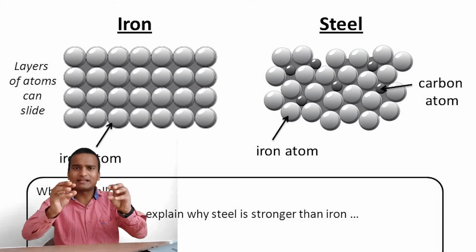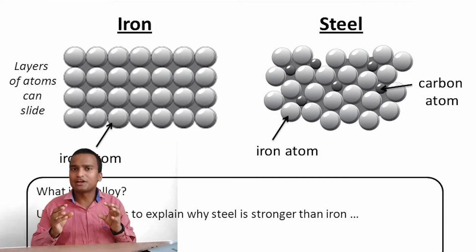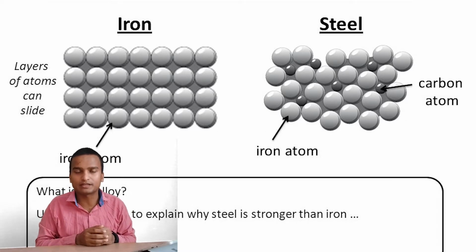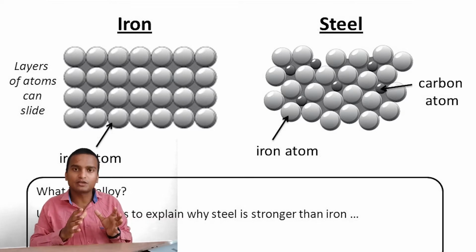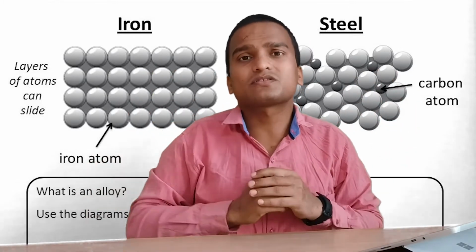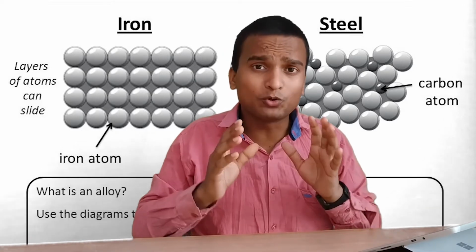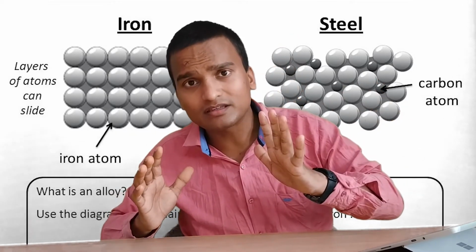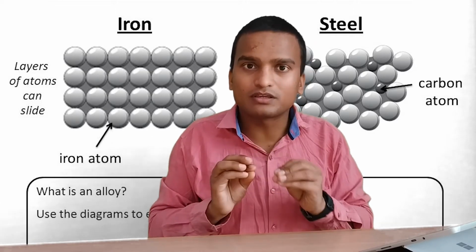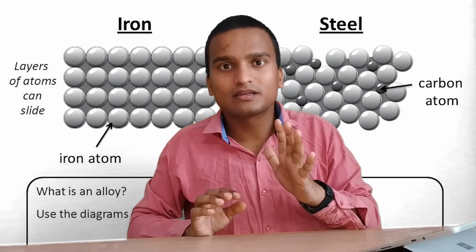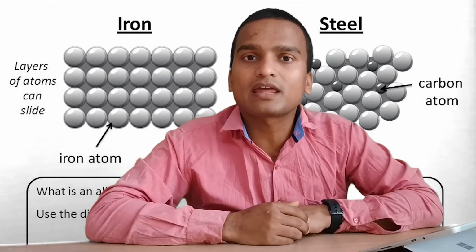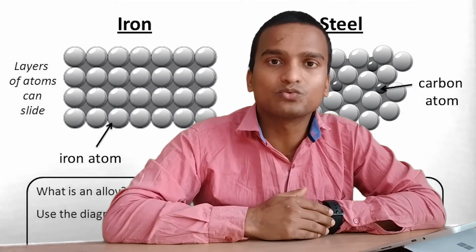Now look, there is an iron lattice which has 8 or 10 or 12 iron atoms, and in the voids between them you put a carbon atom by some alloying technique. So what happens is that the crystal gets distorted, and due to this, when some external force is applied, further distortion of the lattice is avoided. Because when there is a pure iron lattice and you apply force on it, strain comes in very easily. But when carbon atoms are dissolved inside it and you apply force externally, then it resists and doesn't allow dislocation, and that provides mechanical strength in steel in comparison to iron.